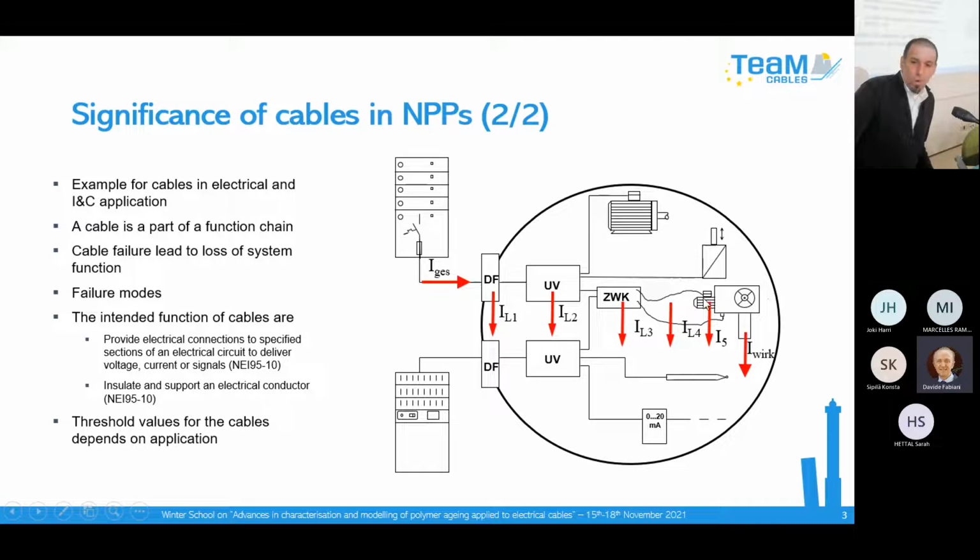So, now what is the reason why maybe we lose the function of this drive, which maybe works to close an important valve? If you have lower insulation resistances here on the cable runs, you have an electrical load in parallel to the motor.